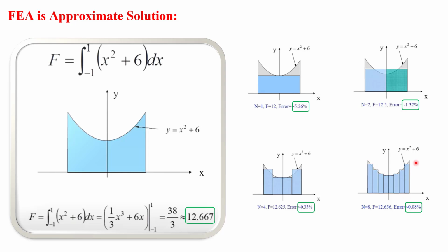In whatever analysis you do, we mesh the model to segregate it into small elements, and then we extract results on those small elements. So the results will be an approximate solution. What percentage error we get depends solely upon your analysis and what kind of mesh you are considering. I hope this is clear to each and everyone.